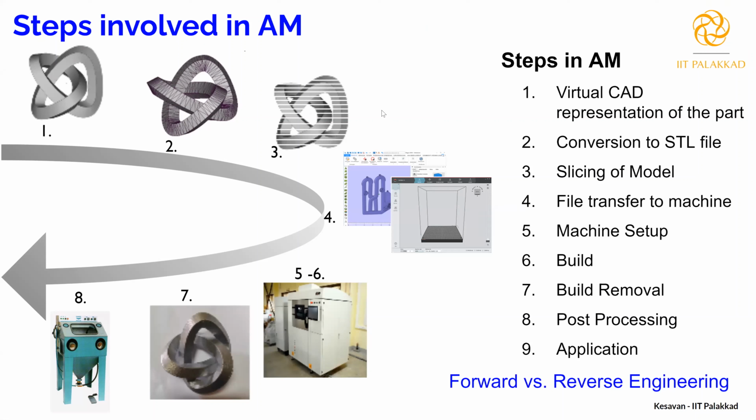I talked about only the bulk components. Let's say the print volume of our machine is about 280, 280, and 320. So the length and width are 280 and the height is 320. To print such a big volume or component, there only we need to take care. But for printing tensile coupons, you don't have to worry. You can print in any direction. It's not a problem.